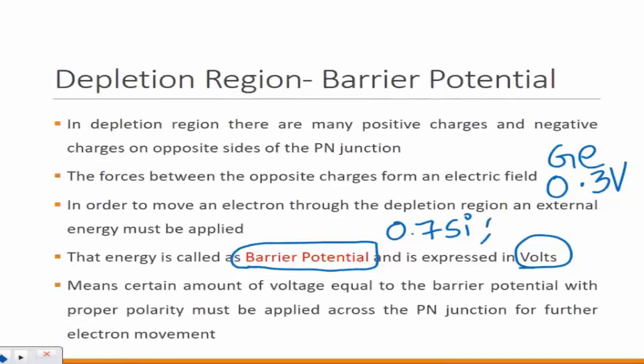Because if you are operating a device at that condition, let's say you find a temperature where you don't need this 0.7 volts, then it's a conductor. Altogether, it acts as a conductor. So why do we need a semiconductor? Or you could use it as a piece of wire. Correct? Because remember that the purpose of a semiconductor is to make it a conductor whenever it's needed, and to make it an insulator whenever it's needed. Right? But if you have no barrier at all, then it's just a piece of wire. It acts like a piece of wire to allow the current to flow throughout.